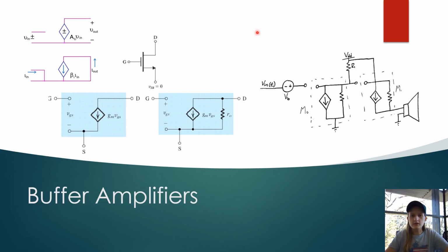So when we break the amplifier circuit down to a small signal model, we get this here. And you can see how the small signal model correlates exactly with the buffer amplification for the current buffer you see here. So this source follower in this part actually acts as a current buffer, which I'm going to talk about. The buffer amplifier is used to transfer current from the first circuit, having a low input impedance level, to the second circuit with a high input impedance level.